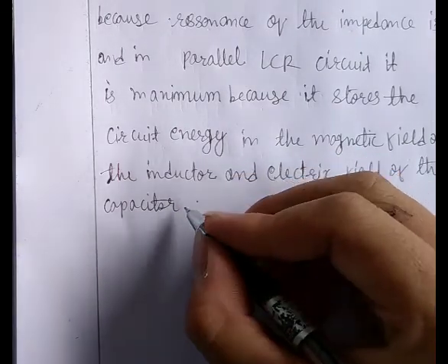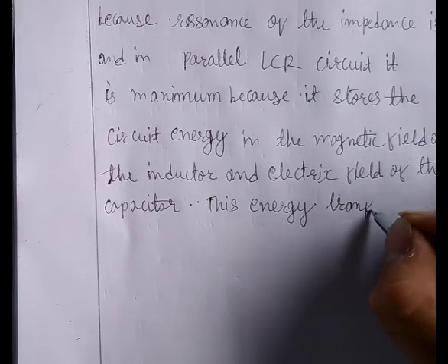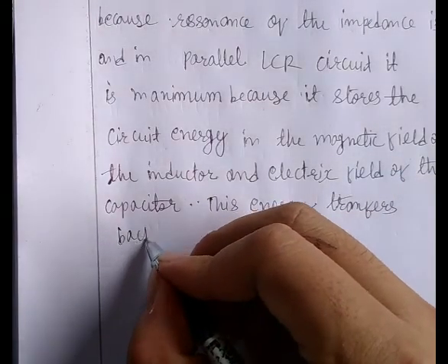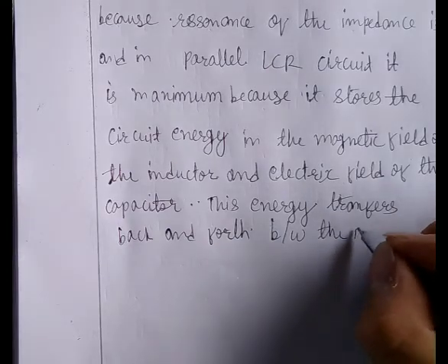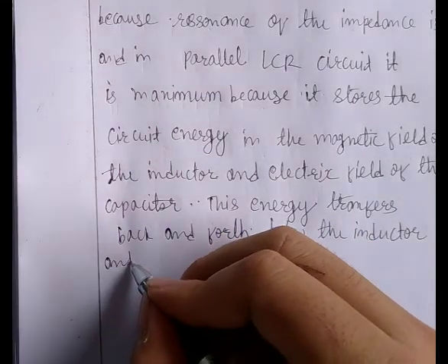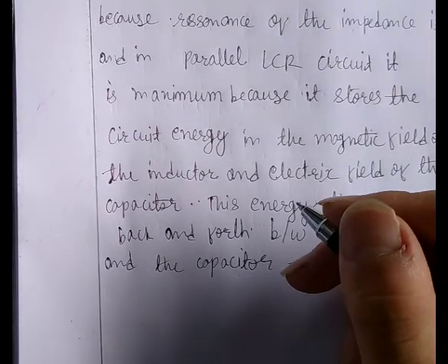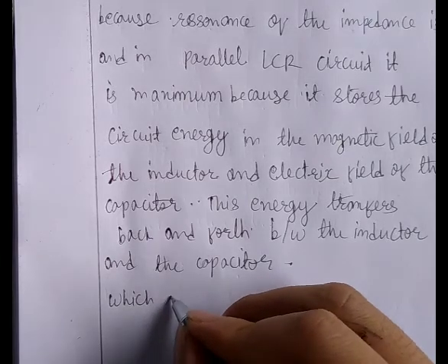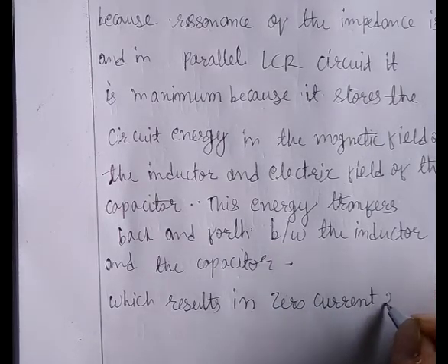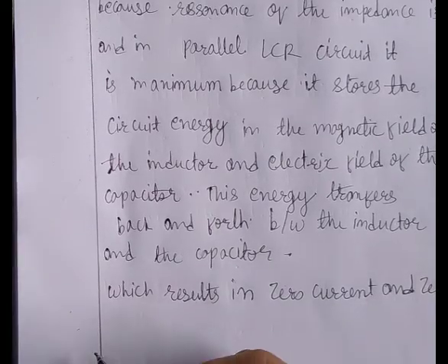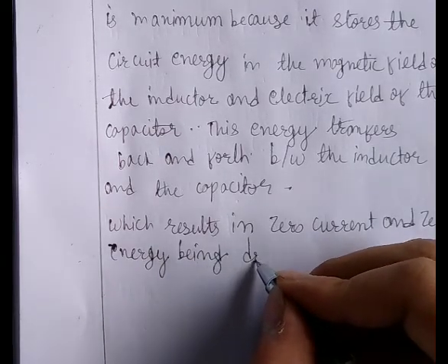This energy is transferred back and forth between the inductor and capacitor, which results in zero current and zero energy being drawn from the supply.